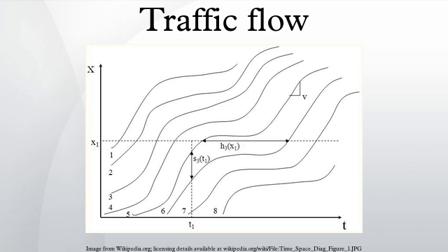However, the concept of the virtual arrival curve is flawed. This curve does not correctly show the queue length resulting from the interruption in traffic. It assumes that all vehicles are still reaching the stop bar before being delayed by the red light. In other words, the virtual arrival curve portrays the stacking of vehicles vertically at the stop bar.